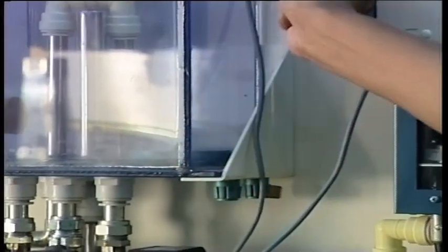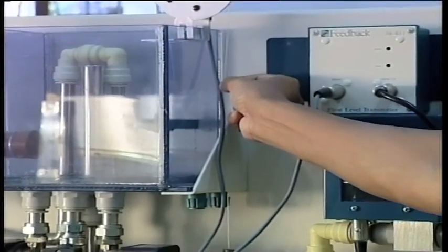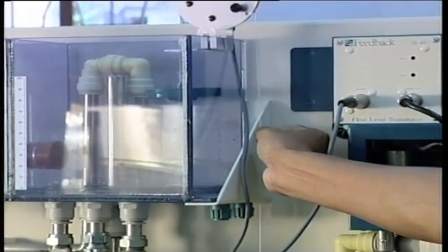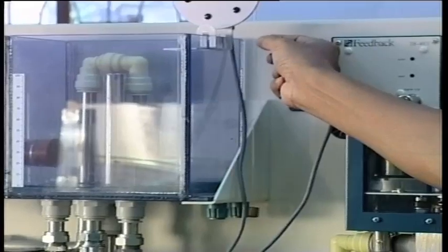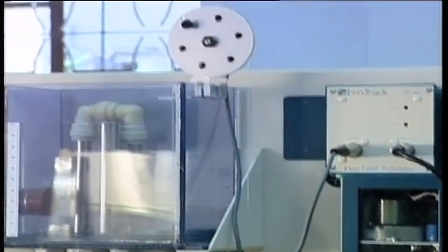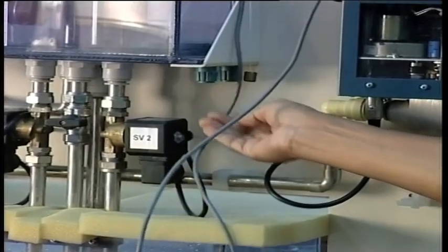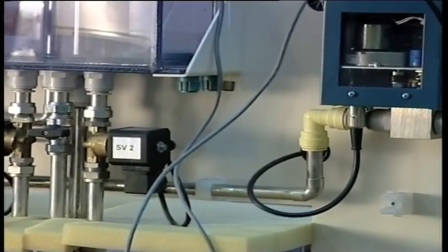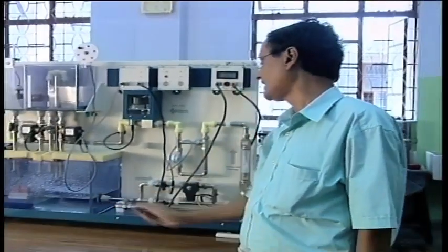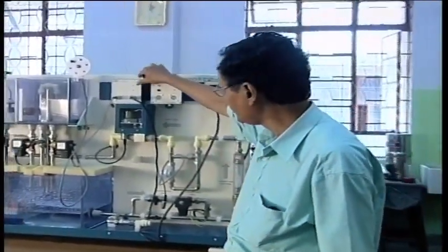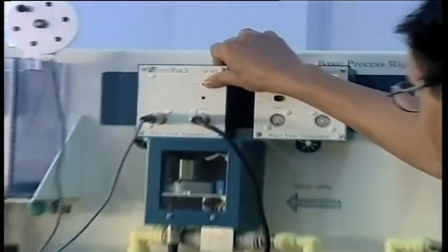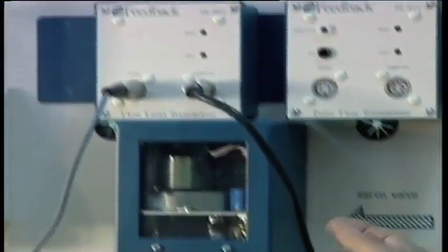Due to the different levels, you can see that the liquid can go up. This float will go up as the liquid goes up, and the potentiometer will move and give an electrical output. In any instrumentation system, one thing we must remember, which will be discussed later also, is that you cannot transmit voltage, you have to transmit current. For that reason we have a float level transmitter which transmits 4 to 20 milliampere of current to the process.